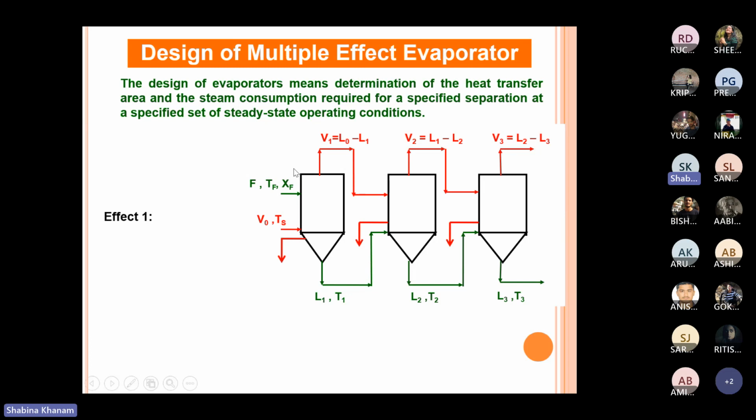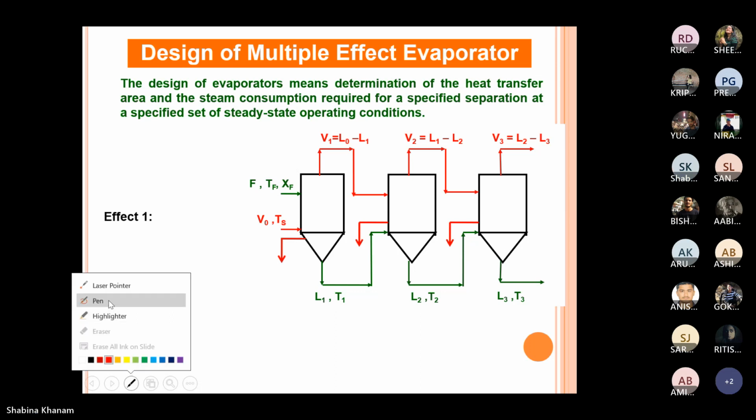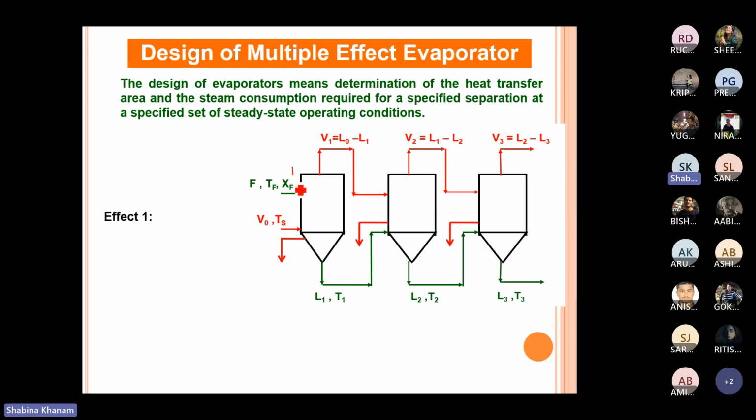So if you consider this first effect, this is the envelope, and when we consider mass and energy balance, we consider only the streams exiting and entering this envelope. So let's make the energy balance.